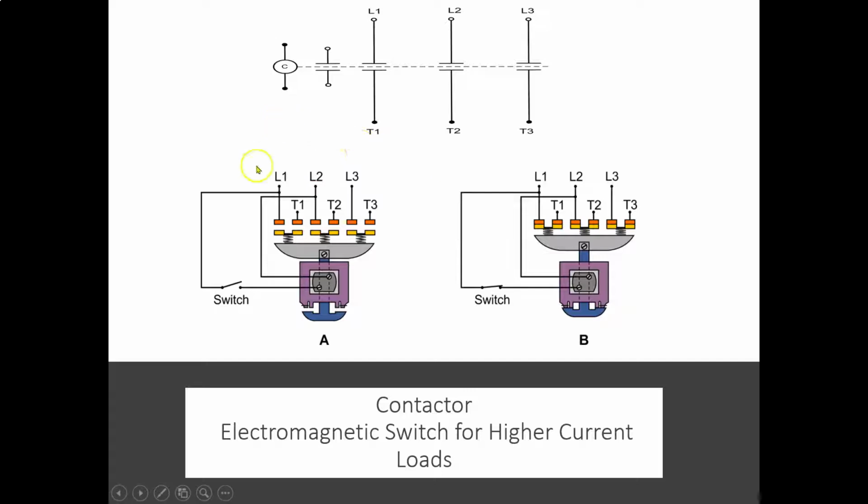So here we have a contactor, a side view of a contactor. We have our coil, which is right here, our core and coil. We have a switch, which is going to be controlling that coil. This blue thing right here looks like a little anchor. That's our armature, right? Hooked up to this armature, we have springs going up to contacts here. And these are called bridge contacts because there are 2 of them for each set.